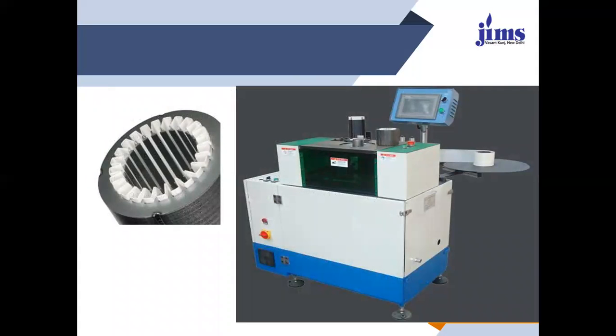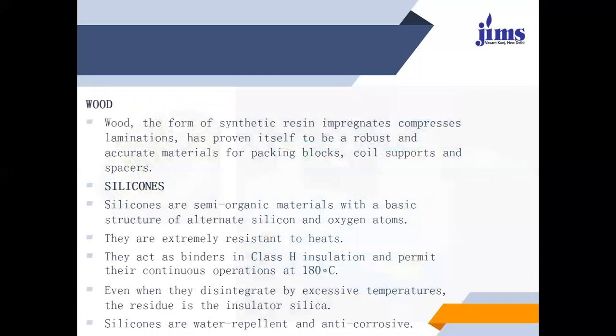It is again indicated for larger machines. If the size of the machine is larger, then automatically the insulation provided will have a different structure, so the size of the insulation will change. This is the machine we are opting for to provide this type of insulation, and this roller helps to place the insulation over the slots of the machine, and it is tightened so that the conductor is never released outside of the body during operation.